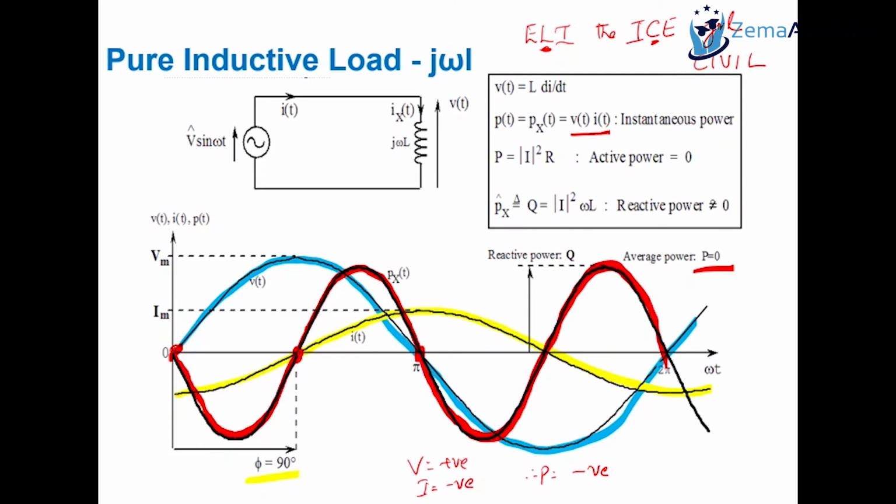Yeah. So when you design cables for a DC circuit, if you say a 5 amp current is flowing through this piece of DC equipment, which could be a heater or something, then that's just 5 amps flowing from the source to the load. But the moment you replace the DC load with an AC load, and that AC load has, let's say, a rating of 5 amps on it, and it has some inductance in it, then that 5 amps might just be the pure resistive current, and the inductive current could be something else, which you need to take into account as well when you do sizing of cables.